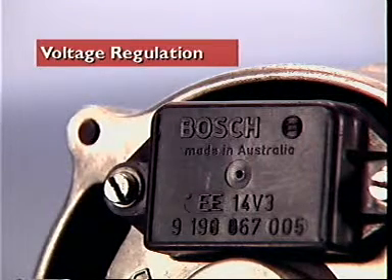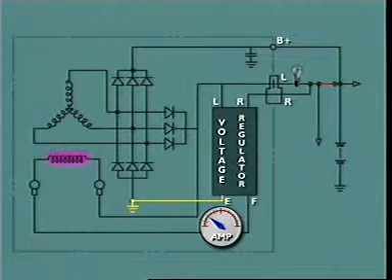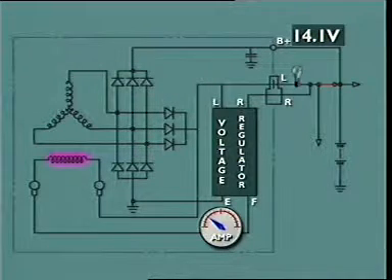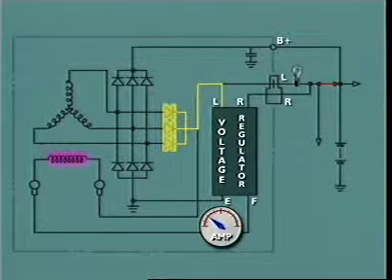This section examines alternator voltage regulation. When the engine is running and voltage output is low, the regulator switches the rotor circuit to ground and maximum current flows through the rotor field winding. The high-intensity magnetic field created raises the value of the induced voltage in the stator windings and alternator output rises. The output voltage is also impressed on the exciter diode circuit, and the output voltage is sensed by the regulator control circuits via the regulator L terminal.